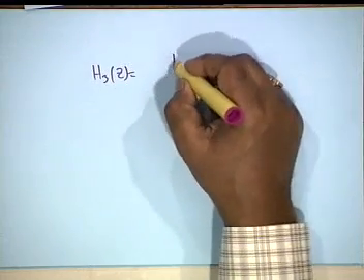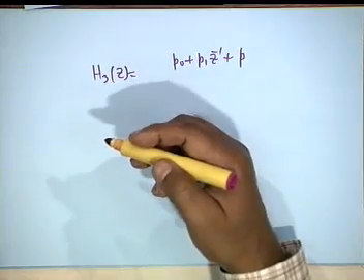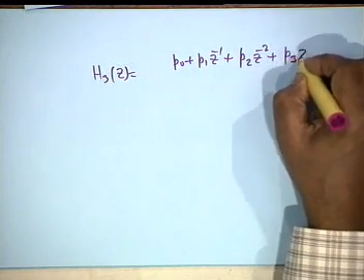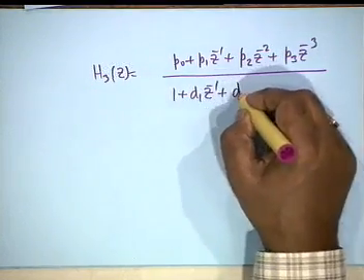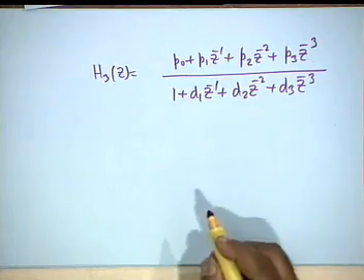The lattice is a structure of a versatile element called an all pass filter, and that is why DSP has obsessions with all pass filters. Just quickly, if you have a third order transfer function, P0 plus P1 z inverse plus P2 z to the minus 2 plus P3 z to the minus 3 divided by 1 plus d1 z inverse plus d2 z to the minus 2 plus d3 z to the minus 3, then you would have realized